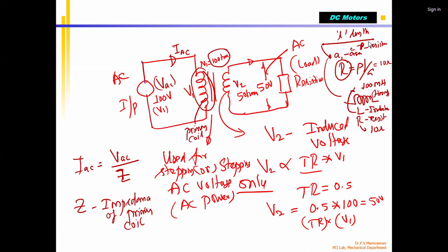Finally, when it is a pure resistance, for the current I, I am applying a voltage, for example, a battery voltage. I have a battery. I am supplying 12 volt DC. This is plus minus DC voltage, correct? There will be a current going, IDC, because of resistance. What is that IDC? IDC equals VDC divided by R. VDC is 12 volts. Already I said resistance equals 10 ohms. So 1.2 amps current is flowing. Correct? Through the wire, current flowing is 1.2 amps.